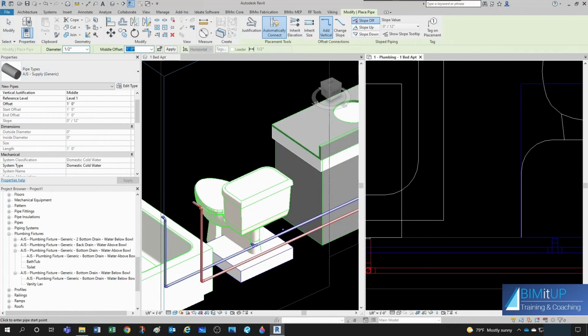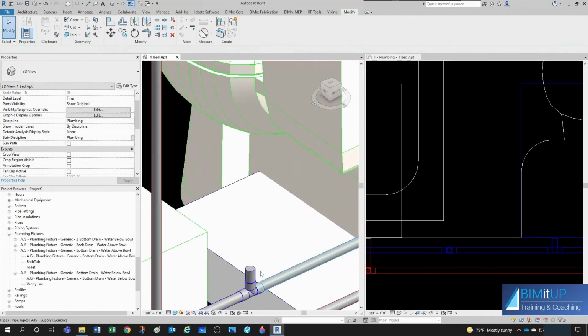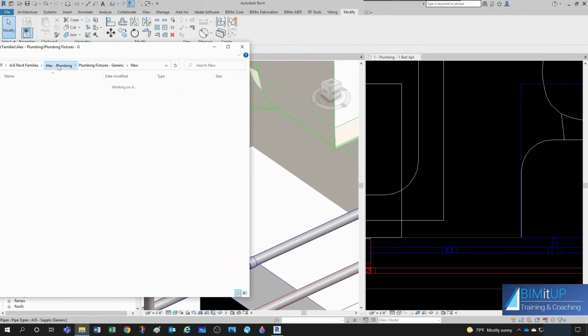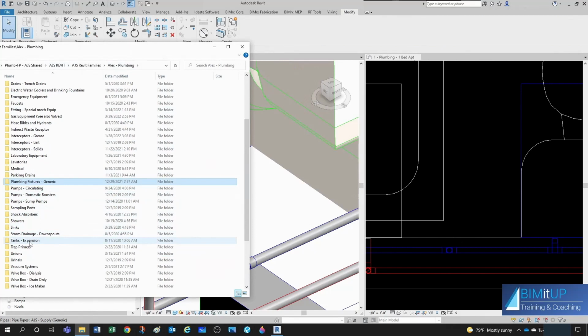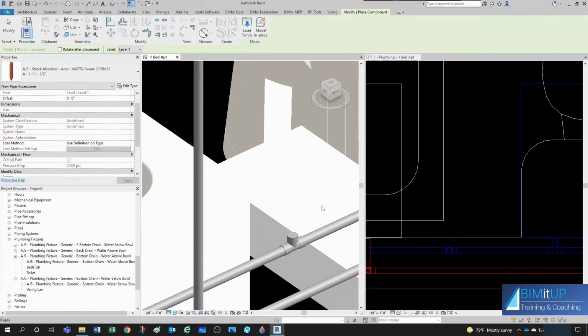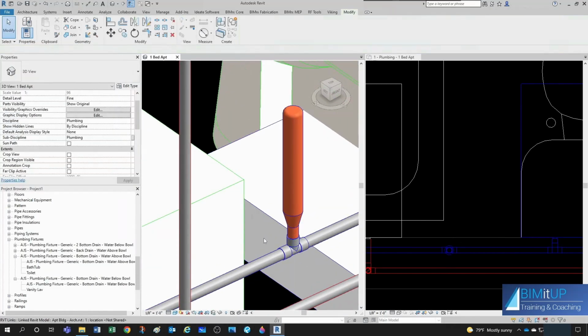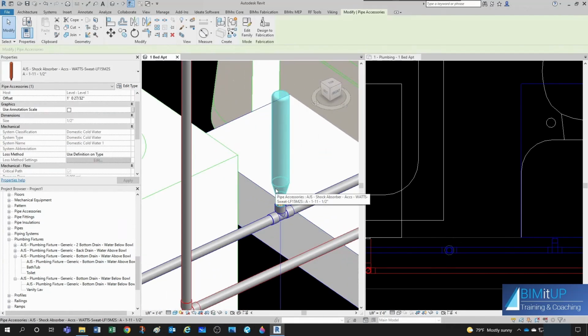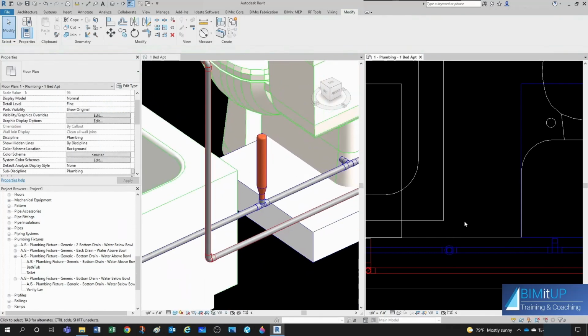So I do create similar, and I do, let's say, 1/4. Then I click here, and if I were to come out like this, see how it creates this riser here? So let me actually delete this rising nipple here and then place my hammer arrestor. That would be under plumbing, shock absorbers, and then I'm going to drop this one here. There you go. You can see that the outline turned blue, so that means that it's accepting it. You want to make sure that you're sizing your hammer arresters correctly. We can see that in another video some other time.